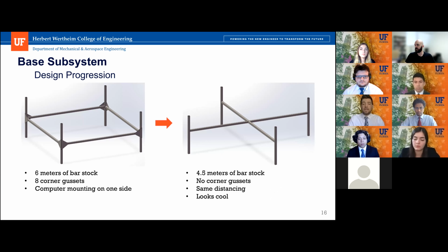Now, our design in our diagrams at the beginning, that showed a square, looked different than the picture at the opening slide. That is a slight design change that we made. While keeping all the parameters the same, the tube thickness, the wall, the height, the spacing, we were actually able to reduce material by using the diagonals rather than perimeters. Other changes we made were we shortened the height of the pole above the cross beams, because we realized that the actuation system actually adds about 3 to 4 inches of lift to lift the reflector up. So we were able to remove that material and lower the cost.